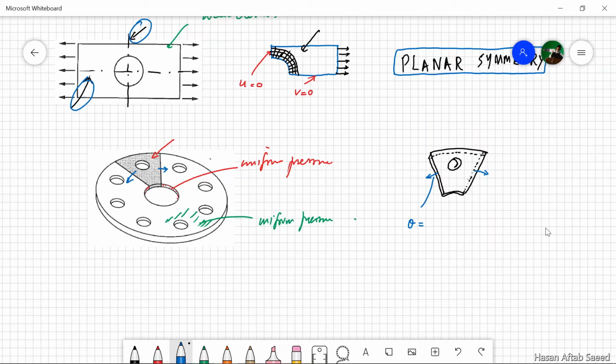All the points on this, in our case there'll be nodes, not points, but all the nodes on this, if they are constrained not to move in the circumferential direction, there's no problem in moving in the radial direction, because as a result of this internal pressure, the new position may be something like this.